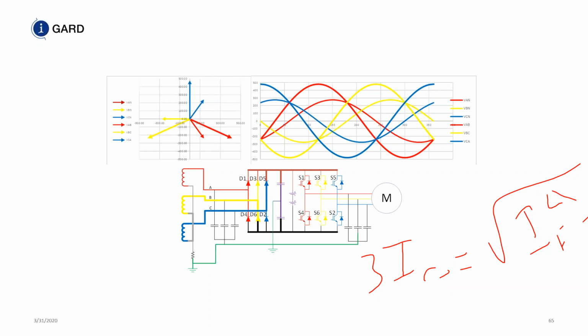We've done it. You can't do this on a solidly grounded system unless you disconnect the solidly grounded system, convert it to a resistance grounded system or ungrounded system, and then measure the current at that time, and then put your ground fault back on, and then put the solid link back on. We've converted many systems from solidly grounded to resistance grounded strictly as an arc flash mitigation technique, and I think there's a webinar coming up in the future for that.